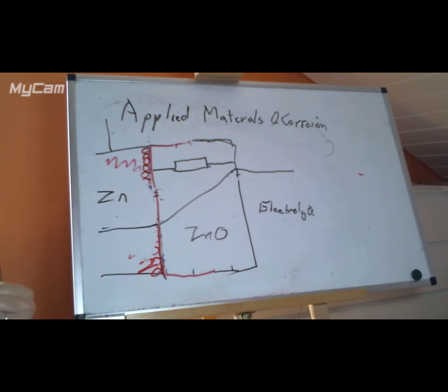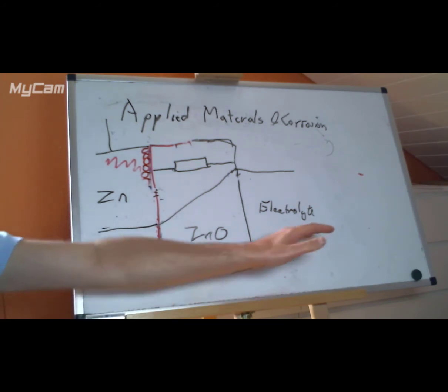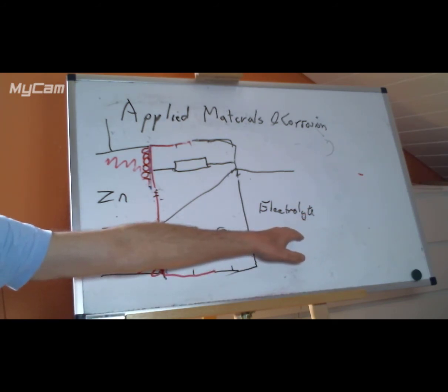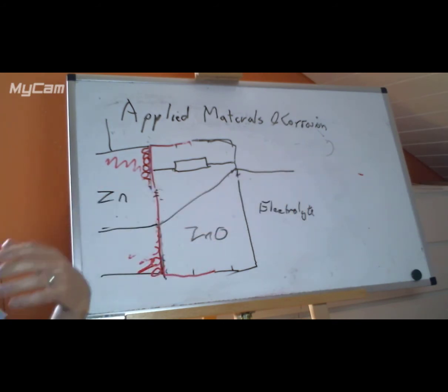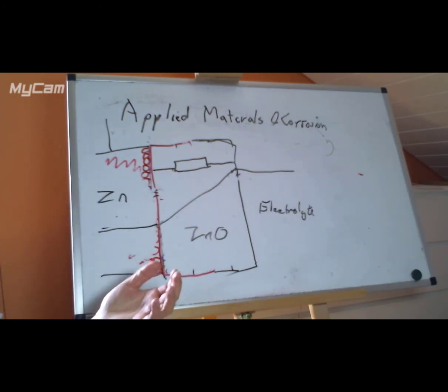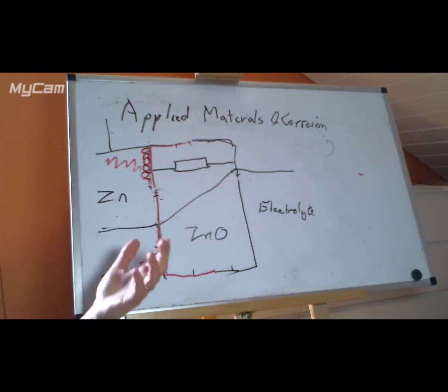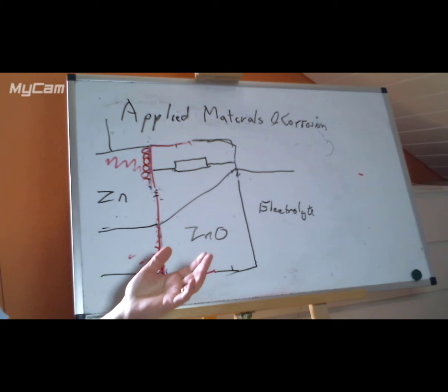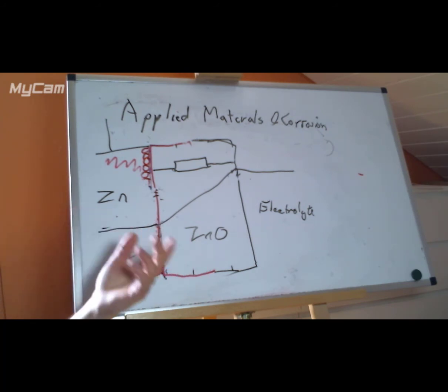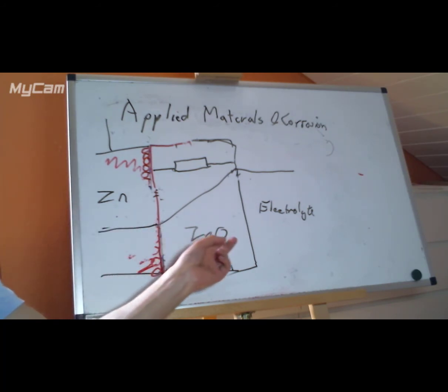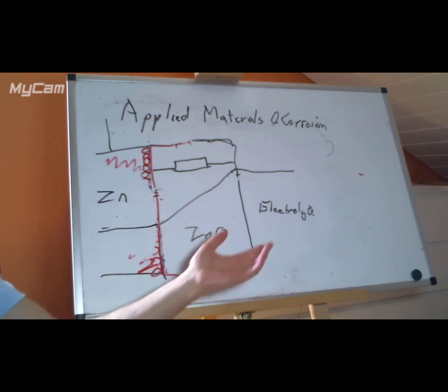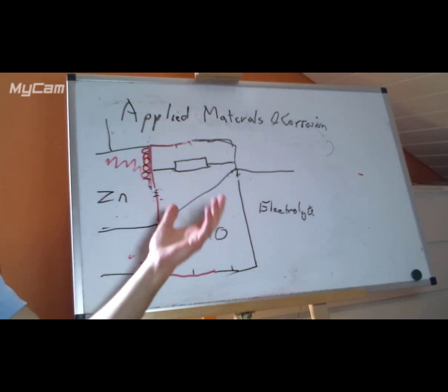Remembering our Pourbaix diagram, the zinc typically is reducing compared to the electrolyte. It's actually below the potential where we would reduce water and make hydrogen. So if we put zinc into water, we should make hydrogen, but we will generate a zinc oxide layer, which is resistive, and the resistivity will slow the corrosion, the oxidation of zinc to form zinc oxide, and the reduction of water to form hydrogen.